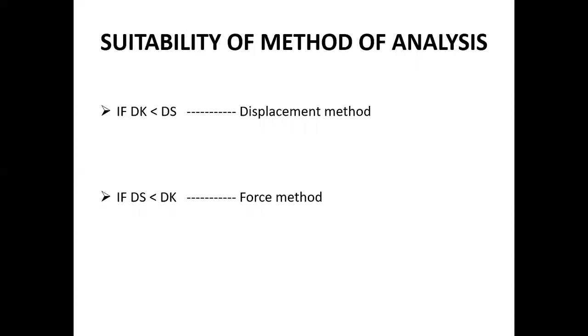If the degree of kinematic indeterminacy is less than the degree of static indeterminacy, in such a case we prefer the displacement method for the analysis. And if the condition reverses, and the degree of static indeterminacy becomes less than the degree of kinematic indeterminacy, then we use the force method. So first of all, we calculate the degree of static as well as kinematic indeterminacy, and then we can decide which method to choose, displacement or force.